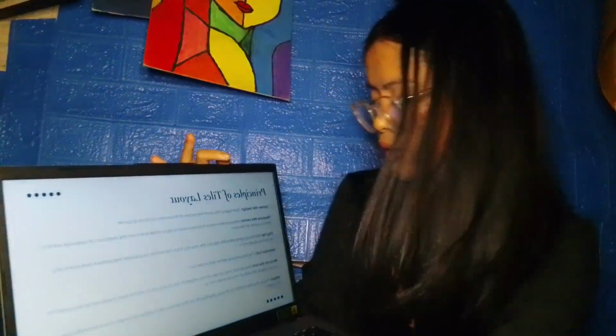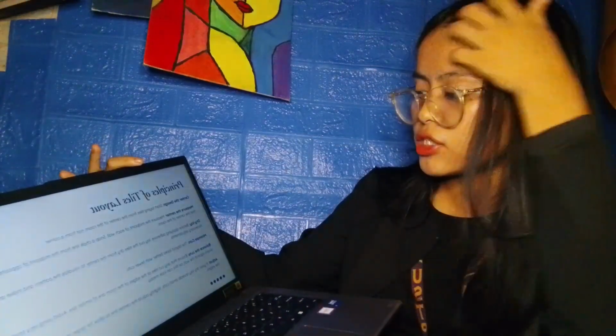And the last one, adjust. If your dry lay reveals small cuts, slightly adjust the center line to allow larger, more balanced tiles at the edges. Okay, again, we have the principles: center the design; second, measure the center; dry lay; minimize and balance the cuts; and adjust.